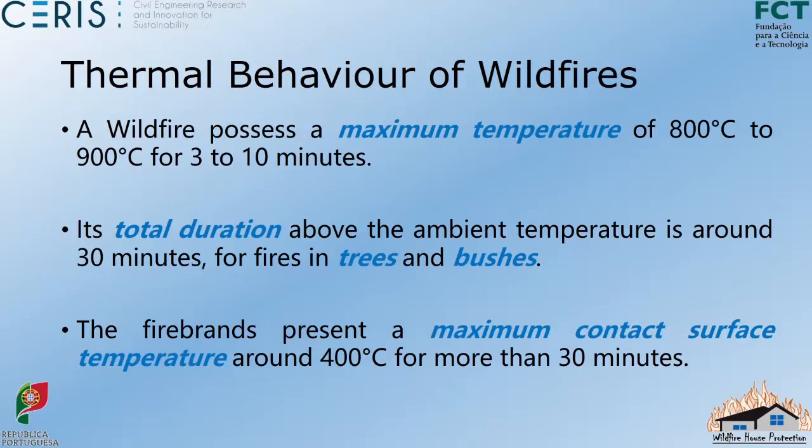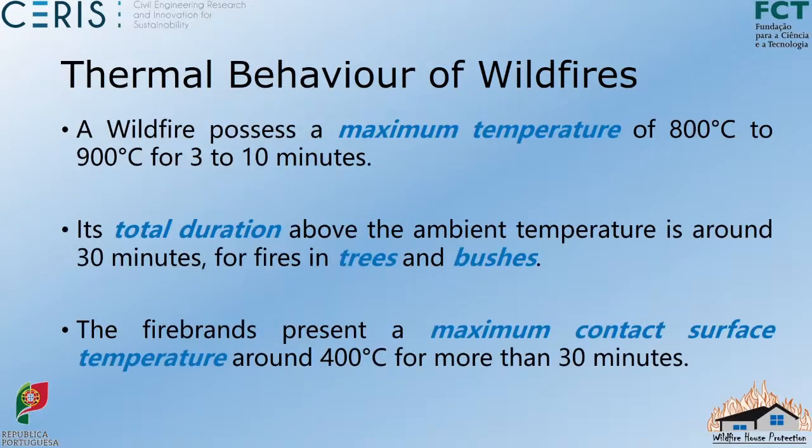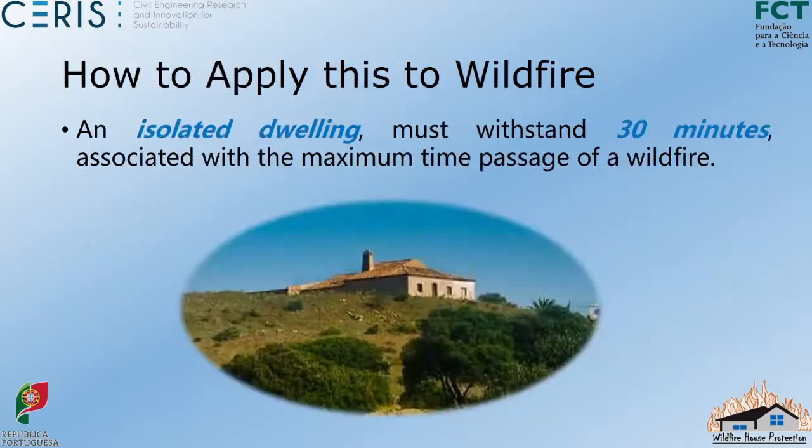Okay, don't forget firebrands, firebrand projections. It's the type of wood that when it burns, it starts flying and starts to accumulate on the surface of the dwelling. So it's the firebrand accumulation that presents this high temperature for a long duration of time.